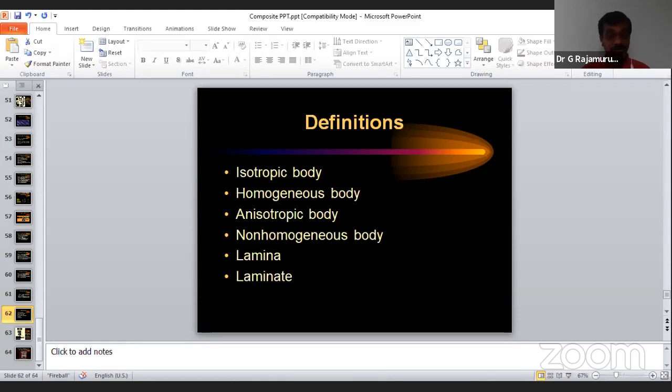Not only that, even in the optimization tools, you can include the speed of stirring. What stirrer speed should I select? Because that also plays a major role. Let us say, can I use 500 RPM or 1000 RPM or 1500 RPM, if you are using a stir casting technique for fabrication of this MMC.